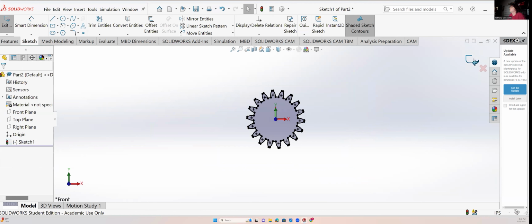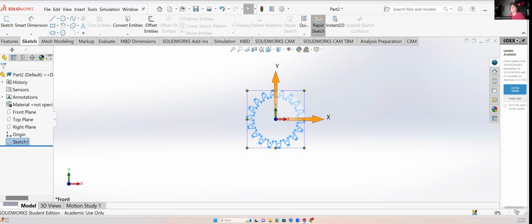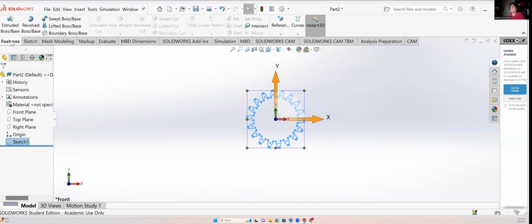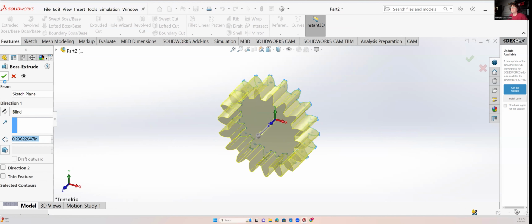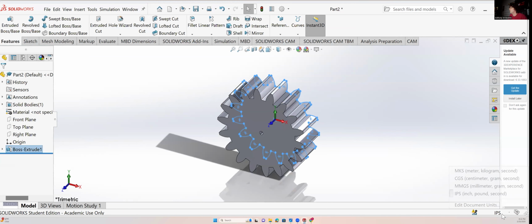Next, we will extrude this. We could extrude this to the 6 millimeter thickness. So we're gonna go extrude above space, and we're gonna make this 6 millimeters. And I've forgotten to change my dimensions once more, so let me do that. Millimeters, grams, seconds. Okay, great.